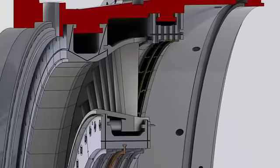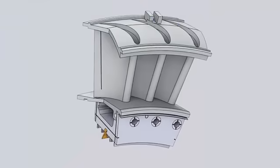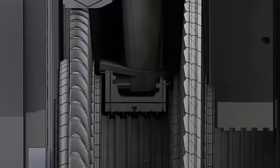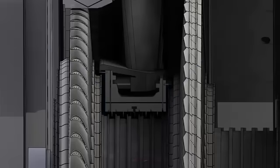The second stage nozzle is cooled by compressor discharge air passing through the first stage shroud. Some of this air exits through holes on the airfoil's trailing edges. The remainder of the cooling air is directed to the first stage aft wheel space through 3 cooling air tubes assembled on the diaphragm. A brush seal segment is installed on the inside diameter of the diaphragm between the labyrinth seals. This brush seal is in continuous contact with the turbine rotor spacer surface to control the amount of the cooling air passing from the first stage aft wheel space to the second stage forward wheel space. This ensures more precise cooling and better unit efficiency.